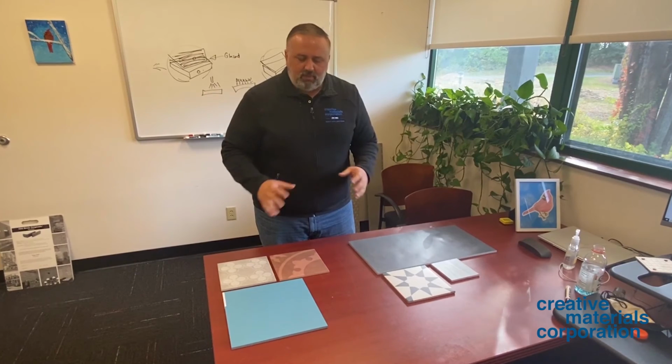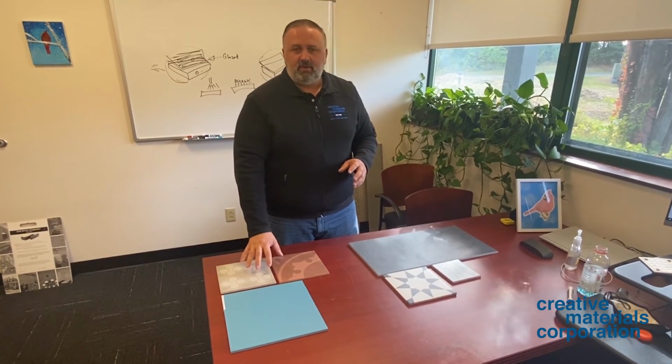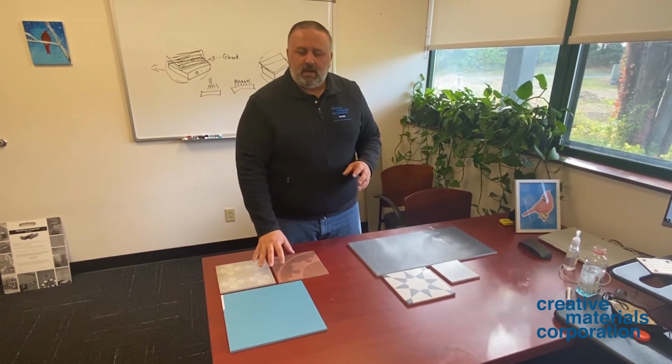These can be used on the floors of more heavy duty spaces, malls, they can be used in train stations, they can be used in airports, for example. Any place where you're concerned that there might be heavy foot traffic, even if it's foot traffic that's in a queue line of a restaurant, for example, where you would maybe be concerned about the wear of a darker color glazed porcelain. Now you can use an unglazed with these aesthetics on the surface and have more confidence without having to go with a through body where you're going to lose a little bit of the aesthetic capability.